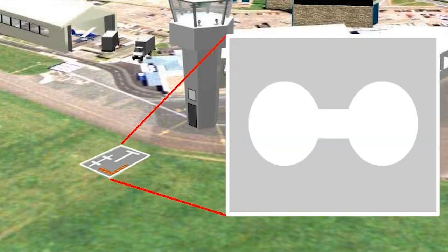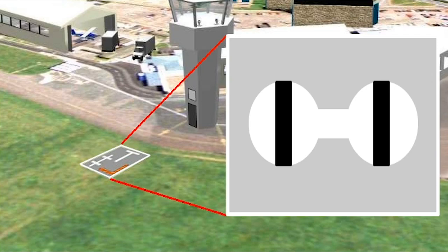A white dumbbell indicates that movements of aircraft on the ground should be confined to paved, metalled, or similar hard surfaces. A black stripe across each disc of the white dumbbell at right angles to its shaft indicates that aircraft taking off or landing are using a runway, but movement on the ground is not confined to the hard surface.